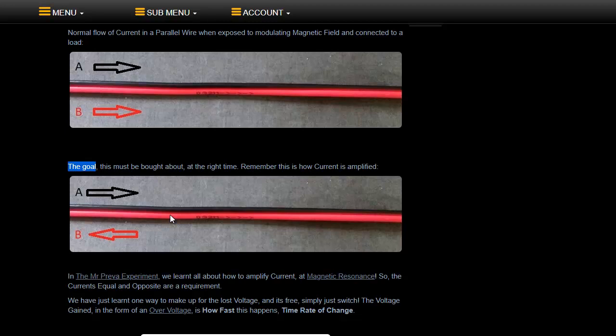People often think of Lenz's law as the force that needs to be overcome, the force of magnetic field or whatever that gives a rotor on a generator drag or torque, which is not the case. Lenz's law predicts the negative voltage in the Faraday's law equation. It doesn't predict current, it doesn't have anything to do with current. It's not current at all.